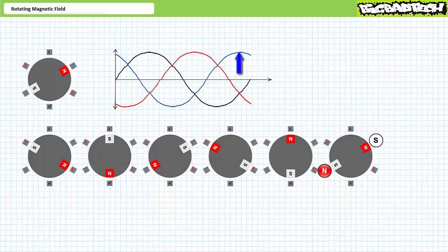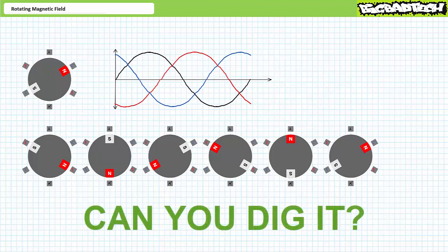The rotor continues to turn clockwise. We're right back where we started, having completed a full 360-degree revolution. Importantly, we completed this full physical revolution in one cycle of sinusoidal AC. Operated at 60 cycles per second, this means a full revolution takes 1/60, or 16.7 milliseconds. If we stood here for 1 full minute, or 60 seconds, we'd observe 60 seconds divided by 16.7 milliseconds per revolution, or 3,600 RPM. Can you dig it?